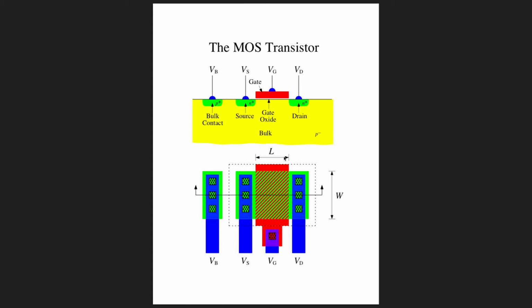If we're working with transistor arrays, that's obviously not something we have direct control over, and they don't even usually tell us what the W/L ratio of the transistors are. But as integrated circuit designers, these two geometric parameters are things we have control over and will often pick to our advantage in doing designs.